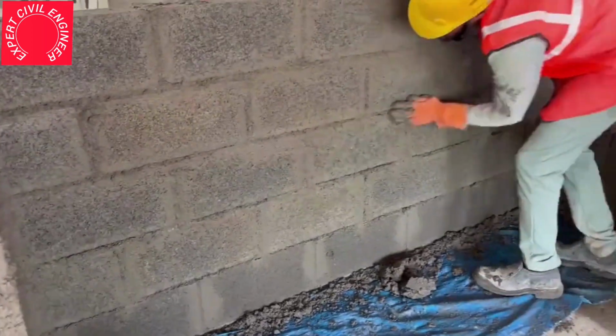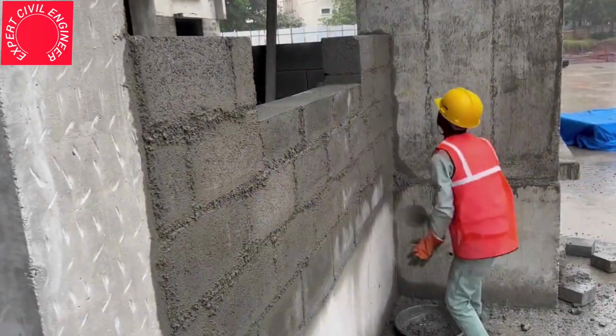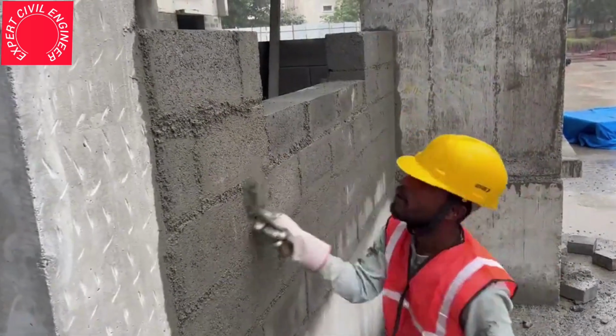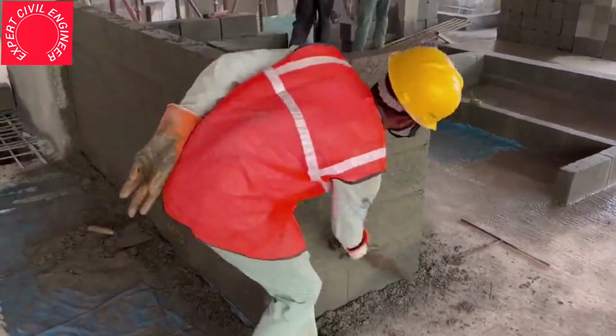Once each subsequent block layer is laid, thorough mortar packing is crucial for both the bed joints, that is the horizontal mortar layer between blocks, and vertical block joints on all wall sides. This ensures complete filling of voids, optimal strength, and a watertight barrier. All excess mortar must be clearly removed from the exposed surfaces of the blockwork.